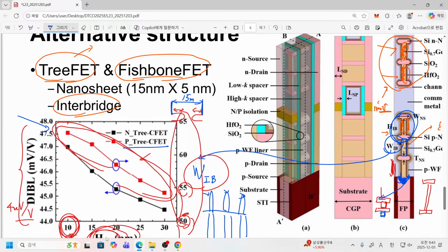So also, we have to consider additional ones because now we have a combination of pure silicon and silicon germanium. What will happen if there is a remaining certain germanium content and if it generates germanium oxide instead of silicon oxide? Then that will introduce some problems in the device reliability. So if we use that device for quite a long time, then something unexpected may happen if we have this kind of potential contributor to the defect.